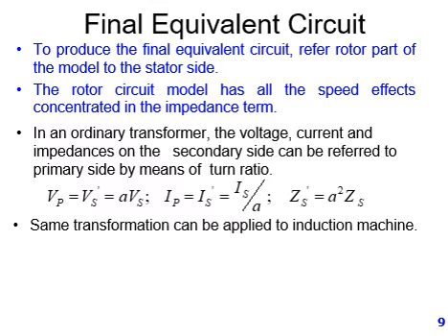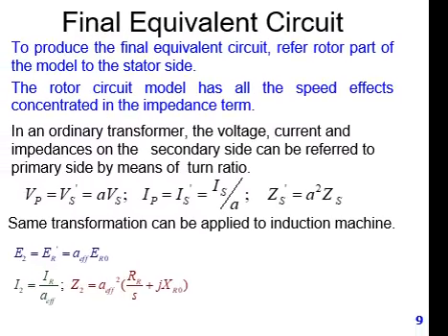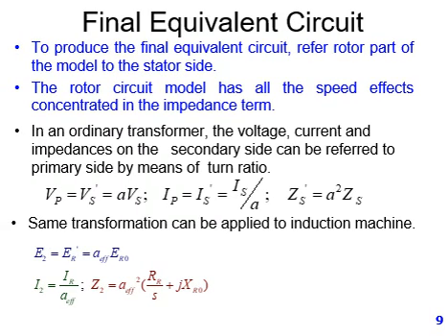To produce the final equivalent circuit, refer the rotor part of the model to the stator side. The rotor circuit model has all the speed effects concentrated in the impedance term.